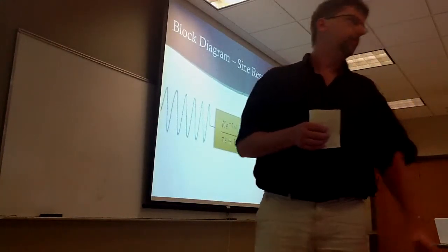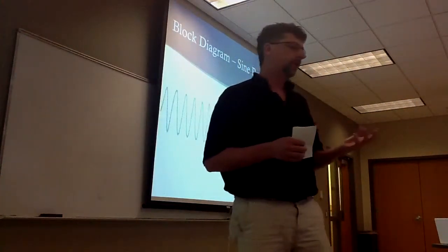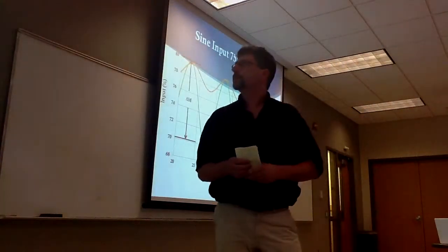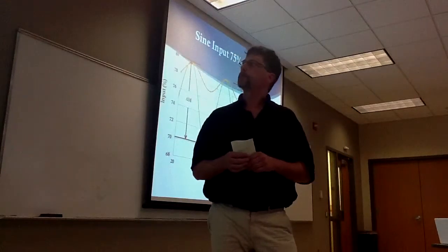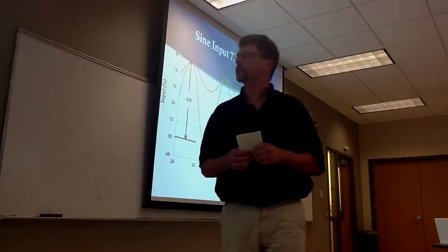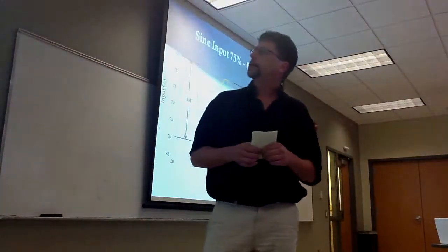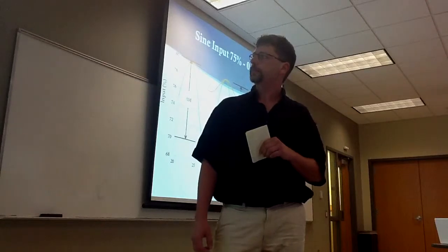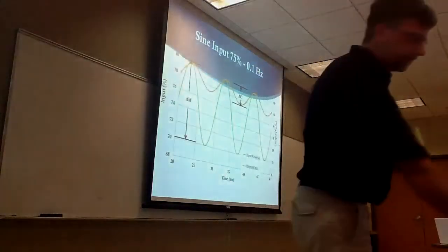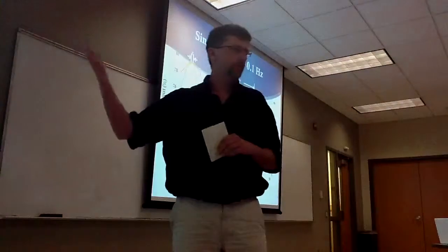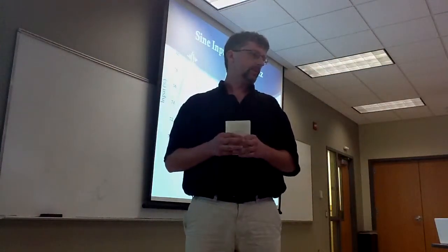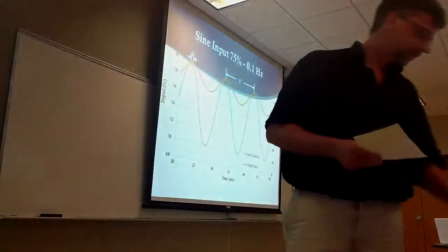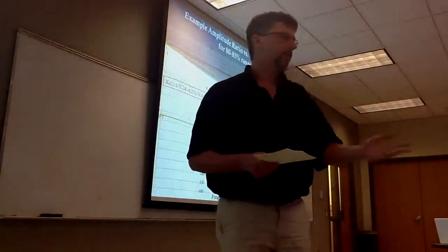The next thing that we did was a sine response, so that we were able to put together the Bode plots. This is an example of 0.1 hertz sine response for 75% input. We calculated the difference here, the delta M over delta C, which gave us our gain, and then calculated the phase shift, the difference in phase angle, to be able to calculate some of the other parameters here. Plotted it all on the Bode plot here.